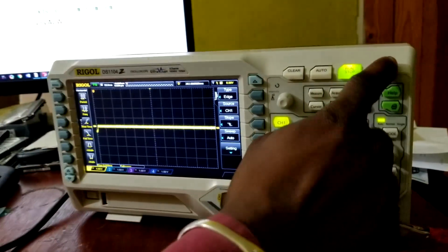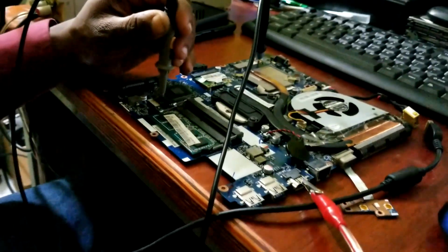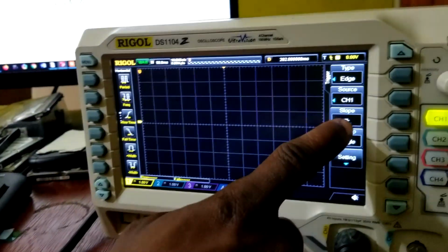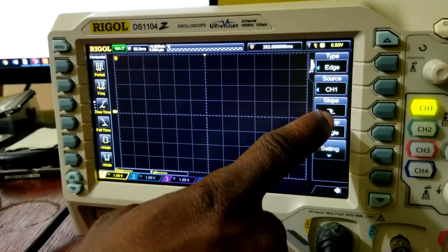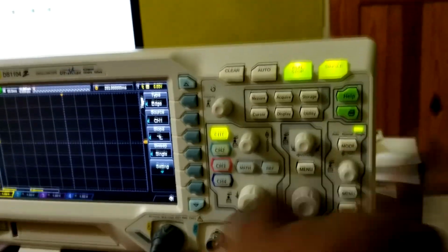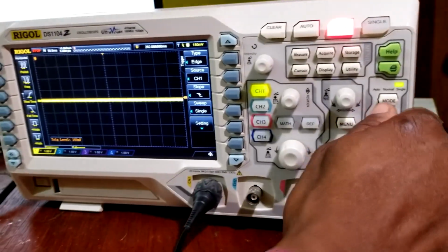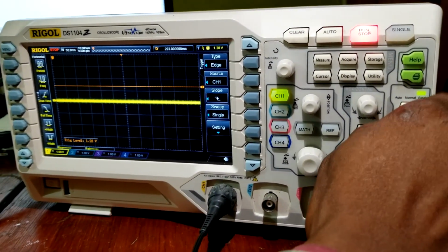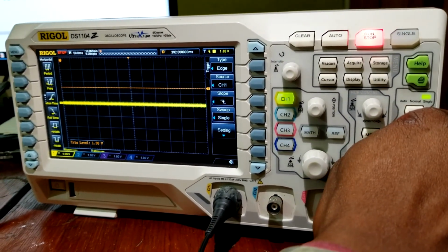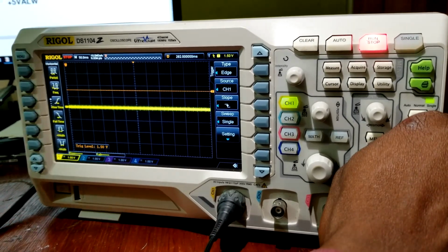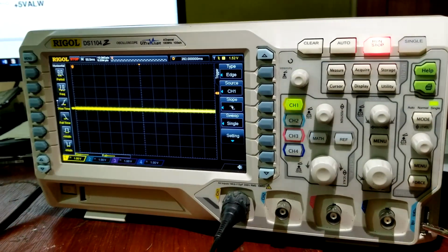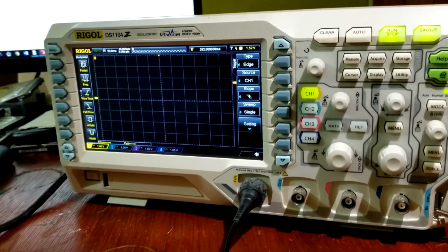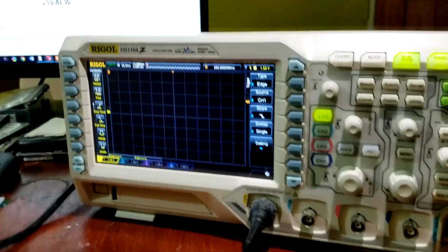We're going to look at the single trigger now. On the trigger, we're going to do the same thing. Now I'm going to set up my control, which is 1 volt per division. The slope is set to falling edge, right? And my trigger set to single. I can now set my trigger level up to about 1.5 volts. All right, my single trigger is set to 1.5 volt there. Now, as I set it back to single, I'm going to connect the adapter.